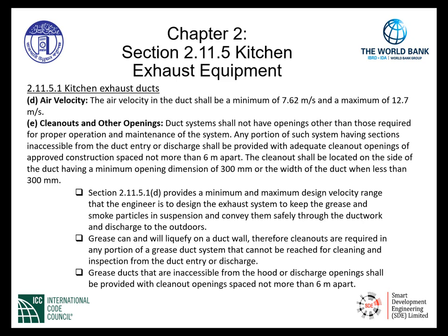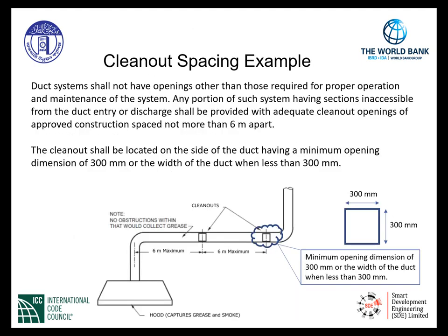The duct system that cannot be reached for cleaning and inspection from the grease duct entry or discharge is required to be spaced not more than 6 meters apart. Grease ducts that are inaccessible from the hood and discharge openings are mandated to be at this particular 6 meter interval and nothing greater. An example of the cleanout spacing is indicated below.